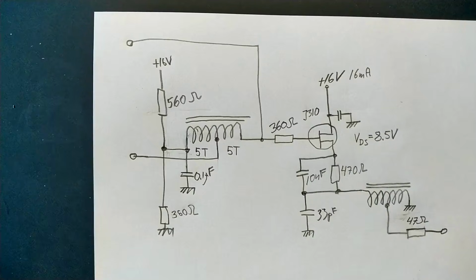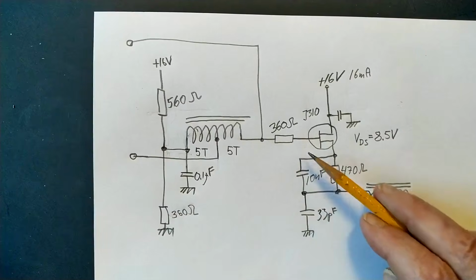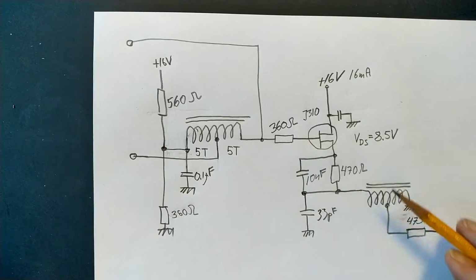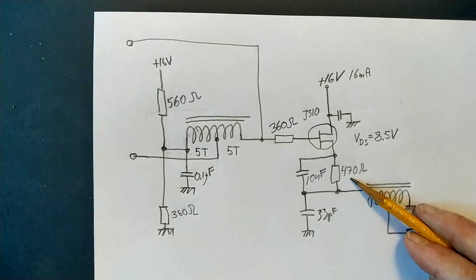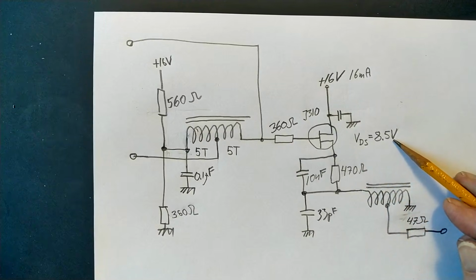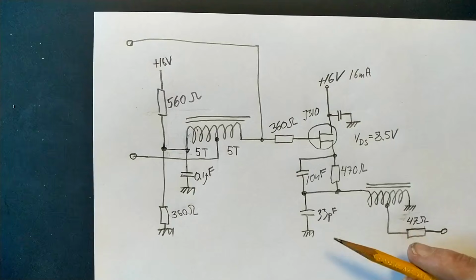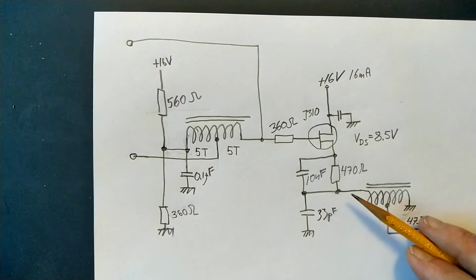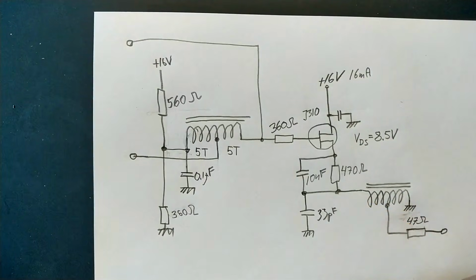I have changed the biasing of the source follower. Means I made this resistor twice as large to bring up the gate voltage. And then I need a bigger source resistor. Now the drain to source is 8.5 volts and the current 16 milliamps. And this is fairly close to the operating parameters I had when running the unit from 10 volts for the power supply. The difference in noise performance is very small.